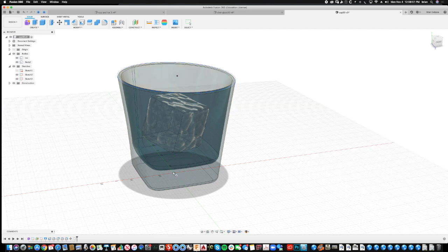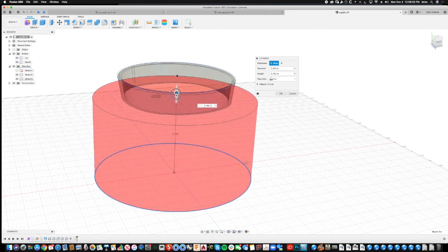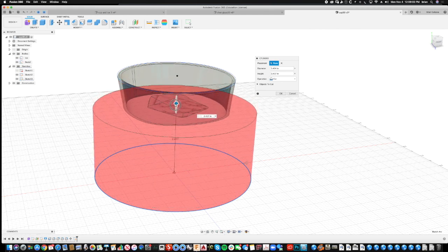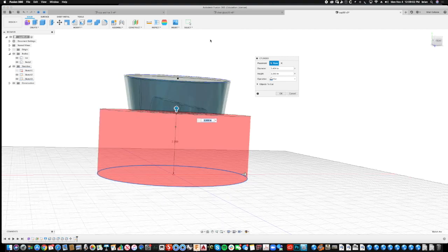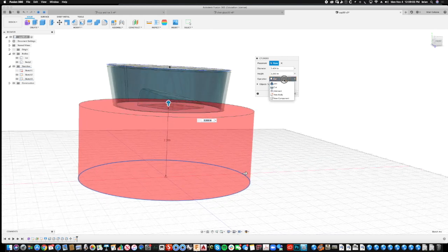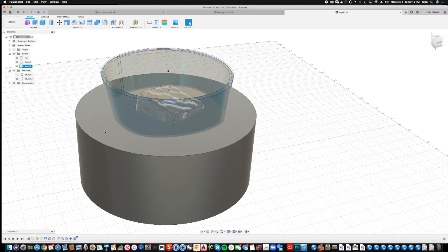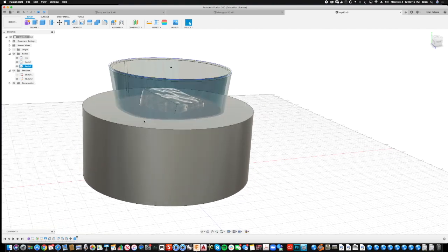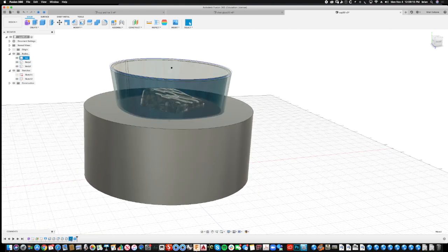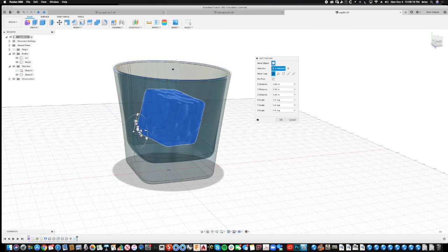So I'm going to select that plane, select the center, drag way out, because this is going to be bigger. And I want the liquid to kind of be up in the top of the glass. Now, it's asking me if I want to cut this. I don't. I want to make a new body. And just hit OK. Actually, since I made this cup bigger, I should probably move the ice up, which was this command. So I'm going to edit and move this up now,